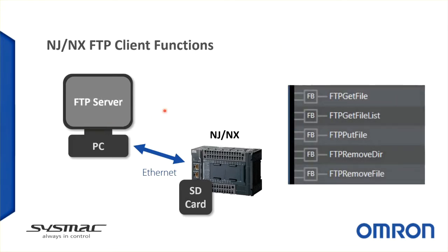The NJ and NX controllers also feature a suite of FTP client instructions for use in your ladder or structured text programs to upload and download files and folders between an FTP server, such as FileZilla server, and the SD card.